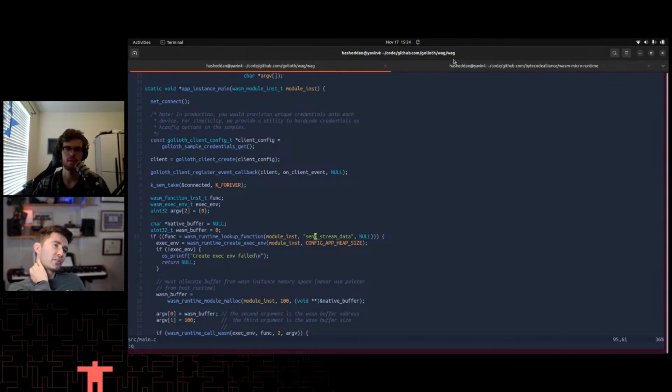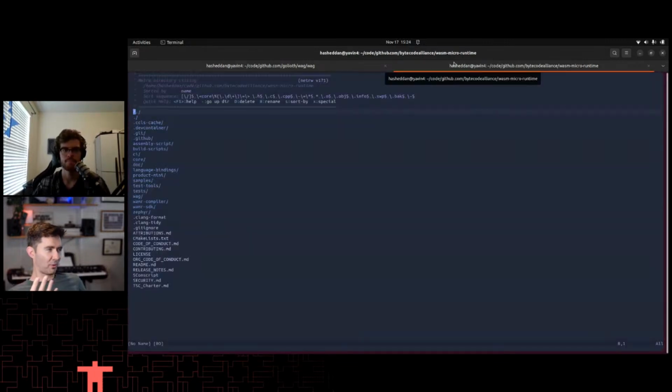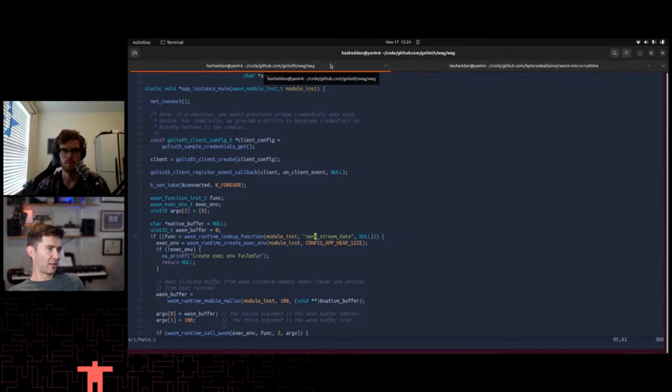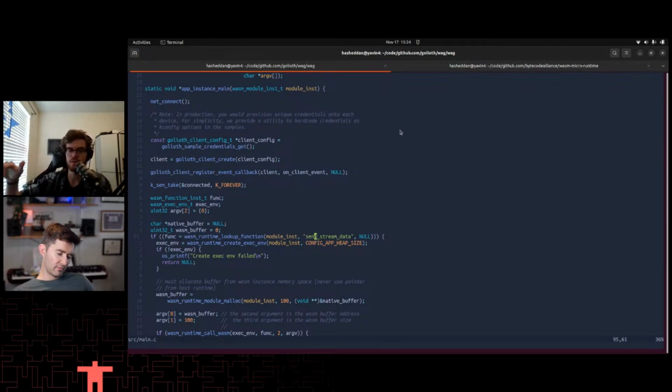This is going to be kind of self-referential, because you could do all this stuff in Zephyr without using WASM, right? That's part of the tricky stuff here. Absolutely. So all we're actually going to do here is ask a function in the WASM module for a string that it wants us to send via Golioth LightDB stream. So you could deploy down a different WASM module that gave you a different string back. So this is just a demo example. You could put some business logic in there and say something like, hey, invoke this WASM module with this data and let it tell me whether I should send the data up or not based on what I give to it. That might be a more real example there.